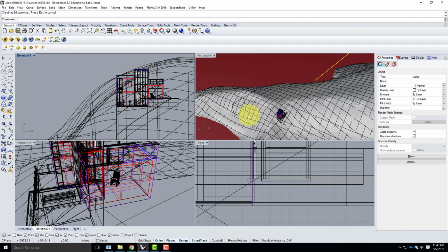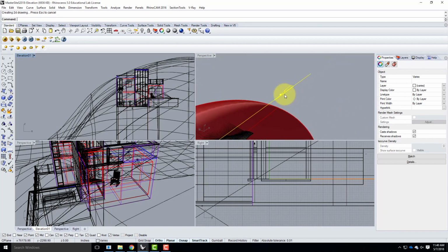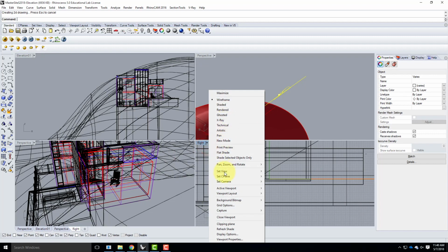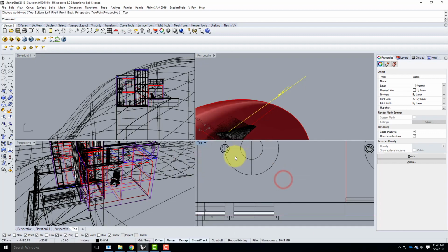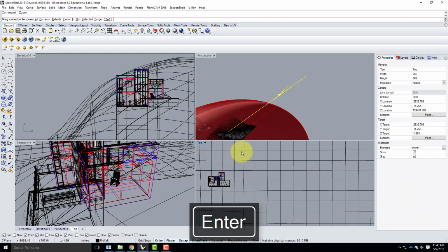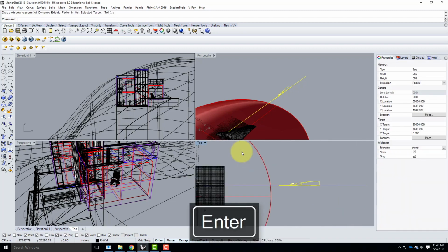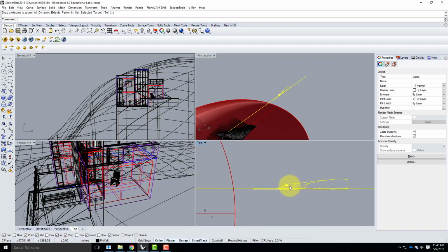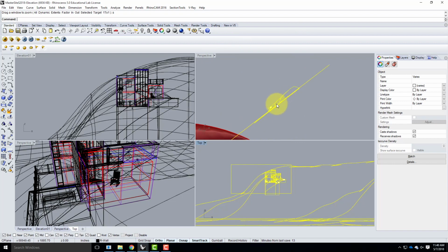And I either have to look in the perspective view, which we're going to be able to see right over here in a second, or I can look in the top view. So if I went on this view to set view and then top, I'd be able to see it. In either view, I'm going to zoom, Z, enter, followed by S for selected, enter, and I'm going to see my 2D drawing. And I'm going to show you this both.